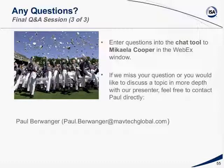Right. We just got 2 questions left here. Would you send an alarm directly to the maintenance crew? That would not be categorized as an alarm. That would be an alert, and you can direct it to them. If you have a separate maintenance workstation, you can do that. It's not an alarm. It's not something that needs to be visible to the operator because there's nothing for them to do, assuming you're sending it directly to maintenance.